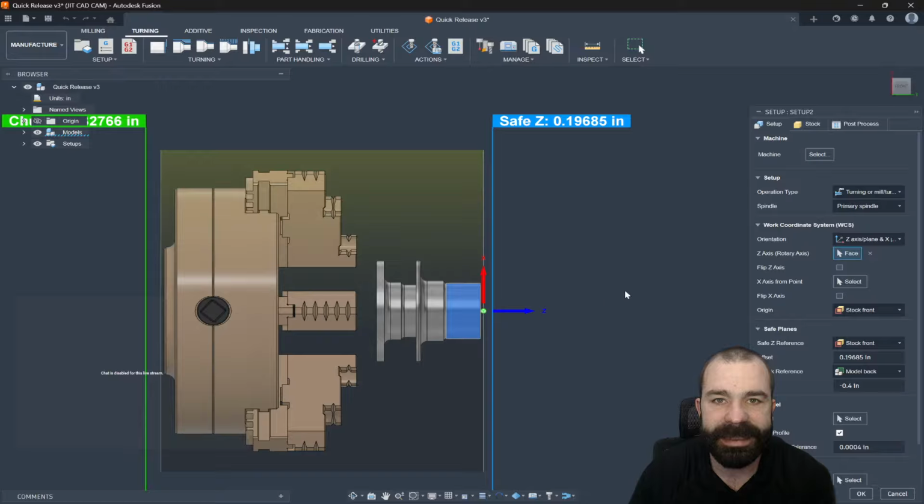Again, on my Z axis, we're usually starting out here at, say, Z 1 inch, and we're traveling, say, Z negative 2 or 3 inches into our part. Again, we need our Z pointed at where our tool is going to come from. This is a little different than milling, but if you always keep this in mind when we talk about the secondary spindle a little later, you'll see why that application is so important.